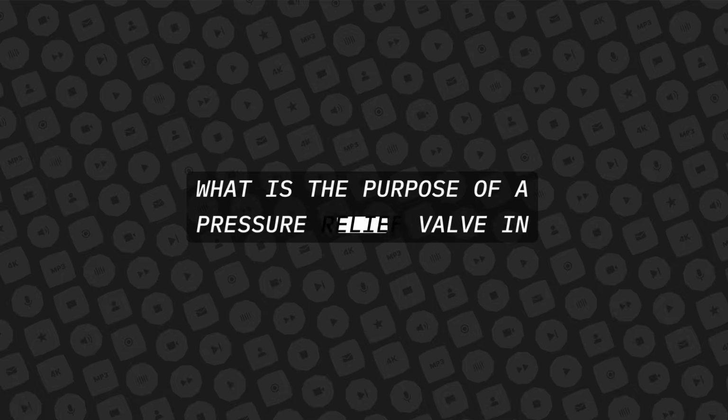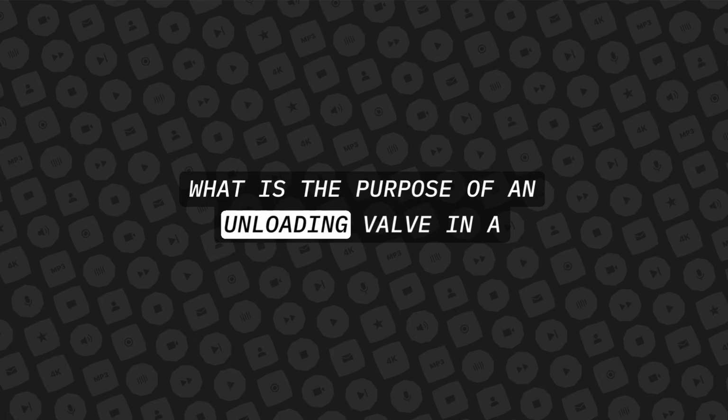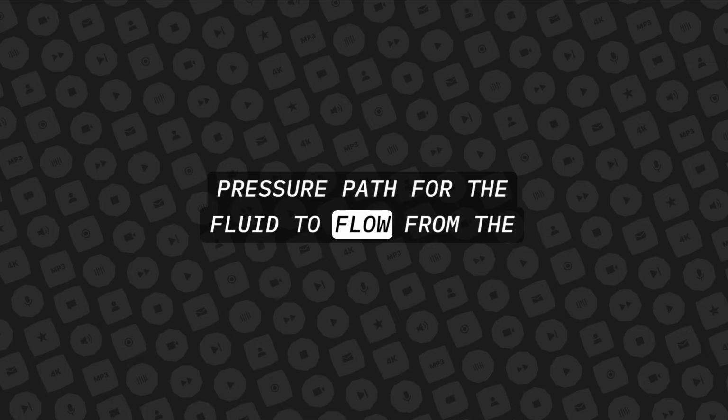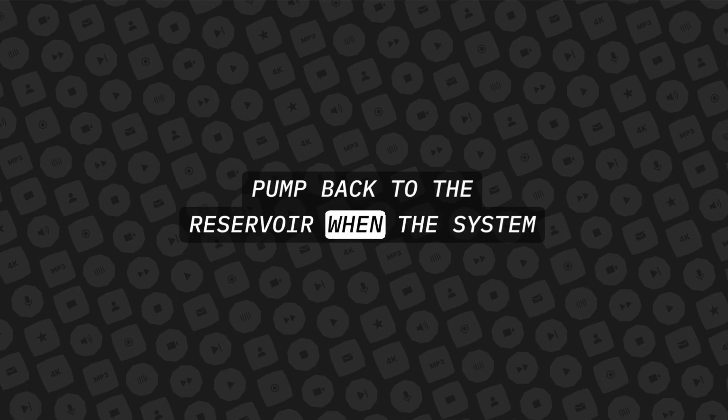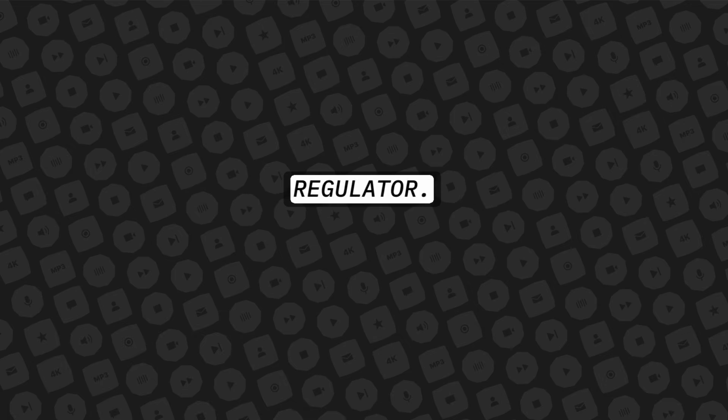What is the purpose of a pressure relief valve in a hydraulic system? It is to limit the amount of pressure in the system. It is, in effect, a system safety valve. What is the purpose of an unloading valve in a closed hydraulic system? The unloading valve is designed to provide a low pressure path for the fluid to flow from the pump back to the reservoir when the system has no flow requirements. The unloading valve also acts as a pressure regulator.